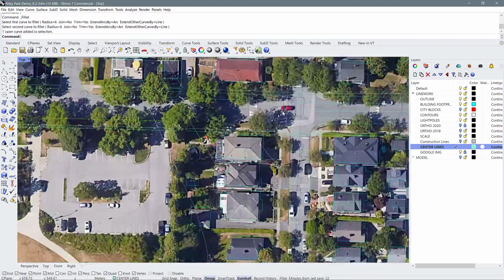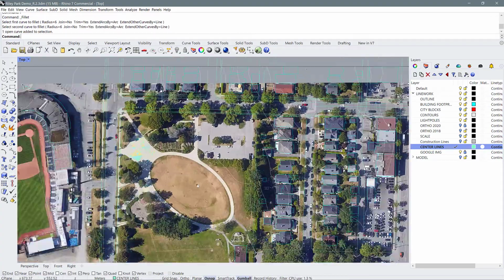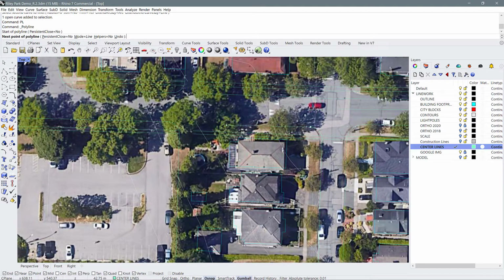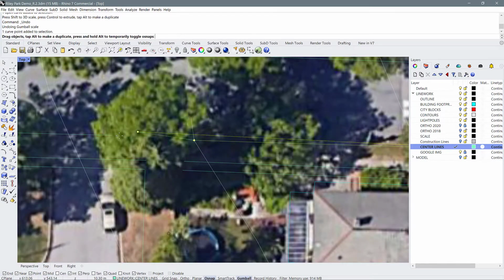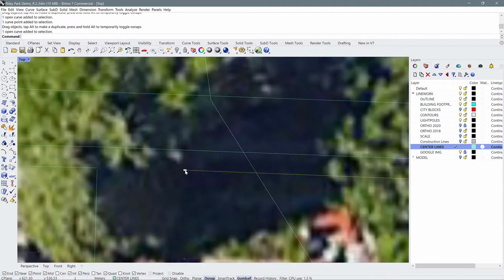All right, up over here, we have an edge that needs to be finished off. So I'm just going to draw a line here. And again, as I said, you kind of have to evaluate the site plan. What I'm noticing is that this curb cut that I've made here is actually not a real curb cut. It's not a real alley. So what I can do is just explode the line using X for explode, get rid of the bit that I don't need. And now I can just drag this polyline control point to the end, and I can control it that way.